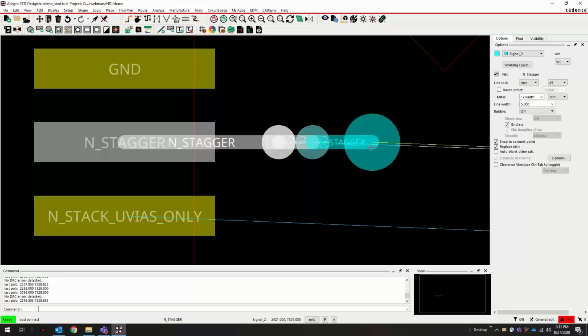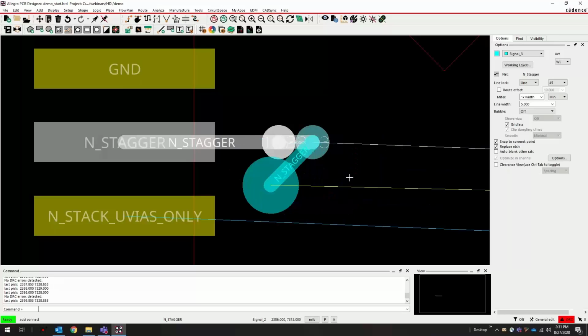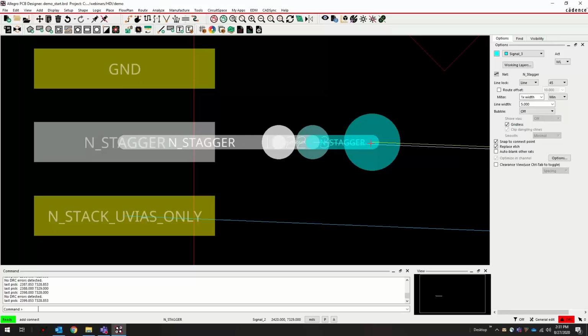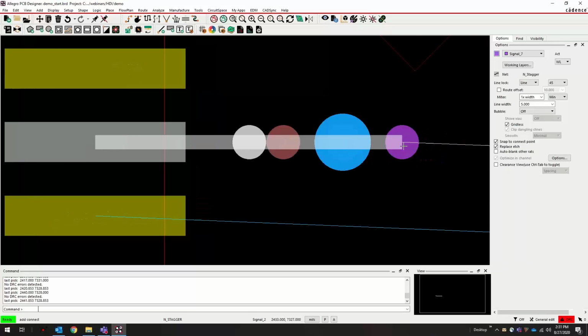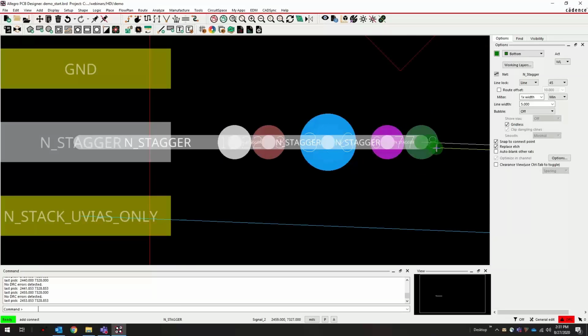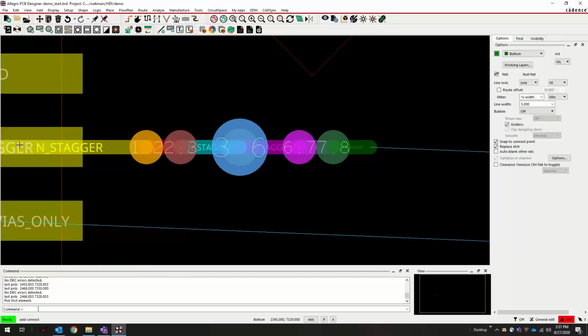So I can place one down, then next on there, it's getting to the next via that it finds to take me down another couple of layers. So now it's the core via attached to my cursor. I can place this down and then back to my microvias. And then now I'm down to the bottom of the board. So you can see here how I've gotten from the top to the bottom of the board using the blind and buried vias that I have set up.